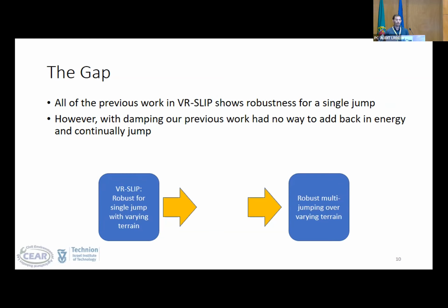Then in a separate experiment, we wanted to show the efficacy of a spiral shaped leg over a straight leg. So we generated 2 legs, each with the same max length, each optimized with the same single jump process, each optimized with torque compensating for damping and SLR for stability, and also for the same rise, the same plus minus 0.05. We set them on a random terrain, and we see that the straight leg deviates from the target Y relative, while the curved leg sort of holds on there. And the straight leg deviates pretty wildly, giving you a higher likelihood of crashing.